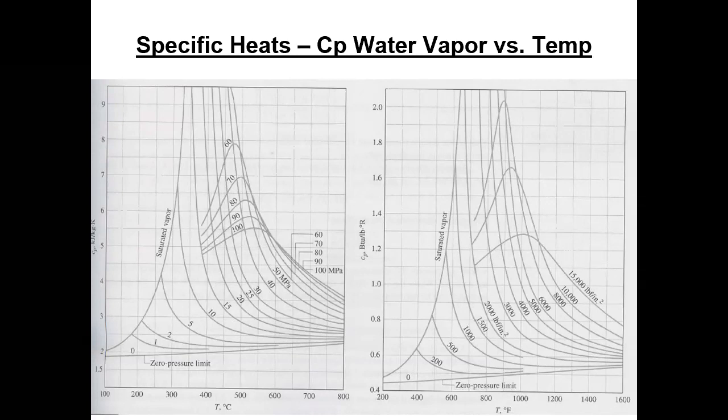Or I can leave it in Fahrenheit and subtract, and I get 100. So now, if it's an application where you're only going to use one temperature, that makes a big difference. If I put in 100 or I put in 560, I get a big difference. But if it's a temperature difference, then it doesn't matter because the conversion factor cancels. You've got one temperature minus another temperature, and so the conversion factor just cancels out. So you've got a positive and a negative value, so it goes away.